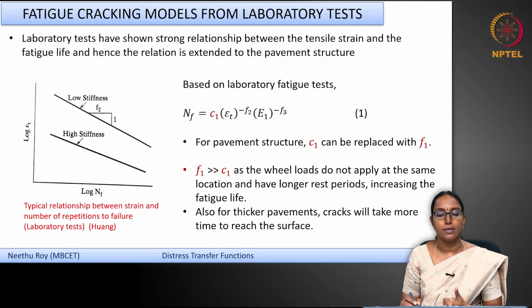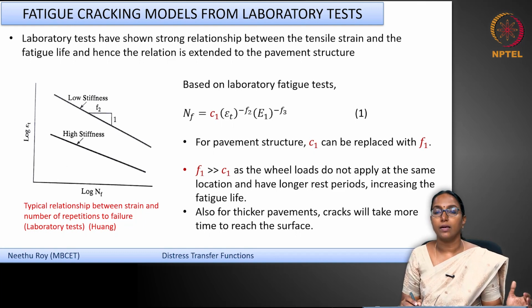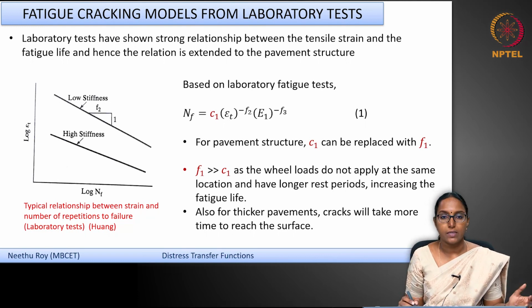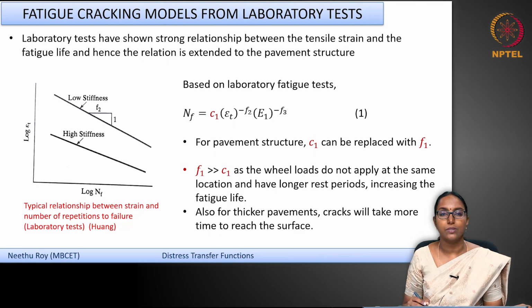Now, first of all, before going into the pavement structure, let us consider the bituminous material. So, we do fatigue cracking analysis, or the fatigue characterization, of these bituminous mixtures. There are various ways by which you do that, and one can always refer to our previous NPTEL course on mechanical characterization of bituminous materials, where we have discussed in detail how this fatigue characterization of bituminous materials is carried out. Now, from such laboratory investigations, it is seen that there is a strong relationship between the tensile strain and the fatigue life.